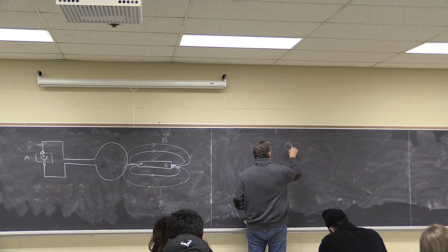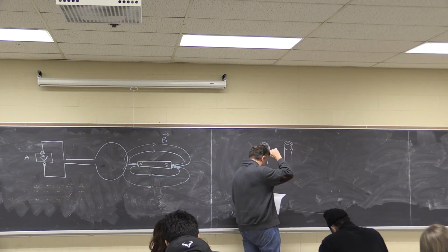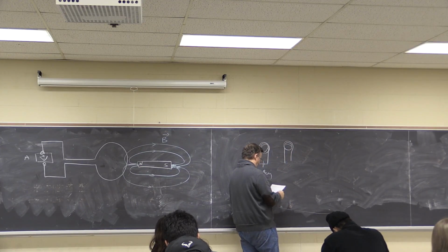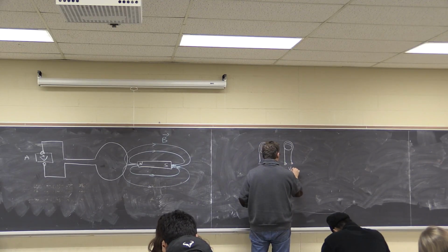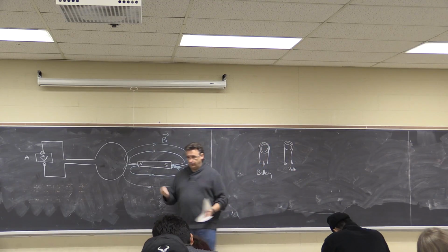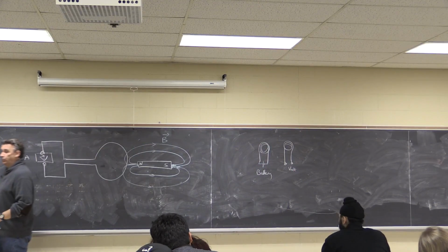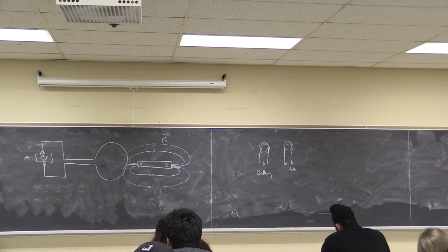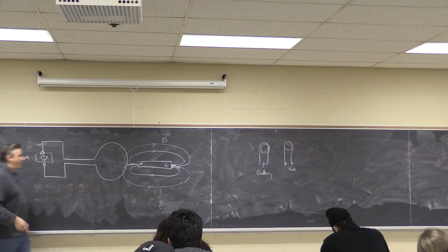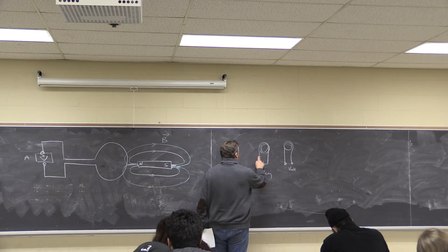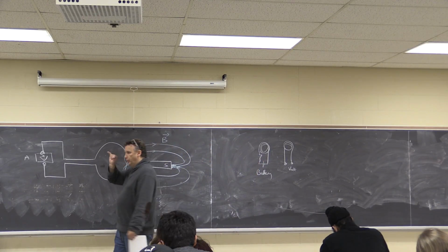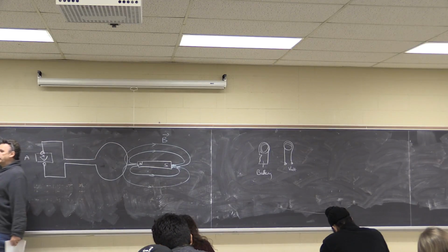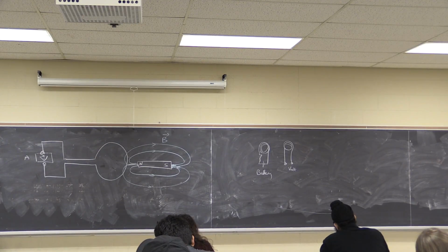If I place another loop of wire here, and connect it to a voltmeter this time, I would see a voltage, which is essentially the same as what Faraday did. But current may be easier to see. So if I put a switch in the wire, when I close the switch, if I measure the voltage, I would get a spike in the voltage when I close the switch, and that then would go back to zero.